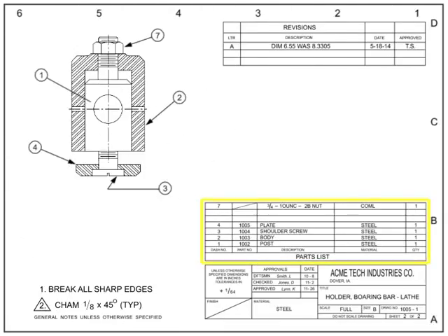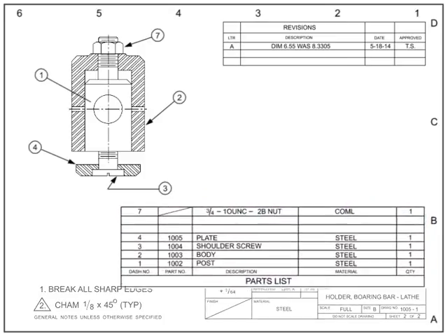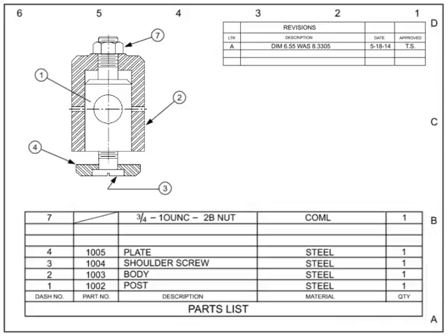The parts list, also called the bill of materials or list of materials, is a tabular list of raw materials or subassembly parts used to make an item. Used only on assembly drawings, parts lists are typically located directly above the title block, although some drawing standards put the parts list on its own sheet or even as a separate document.